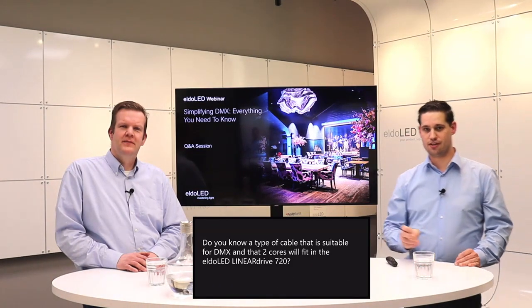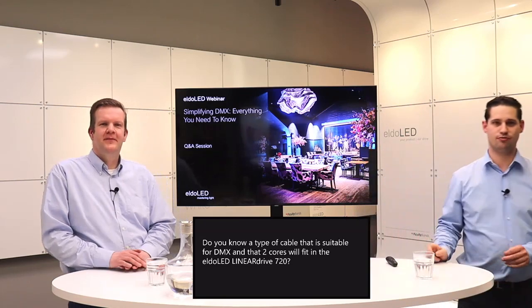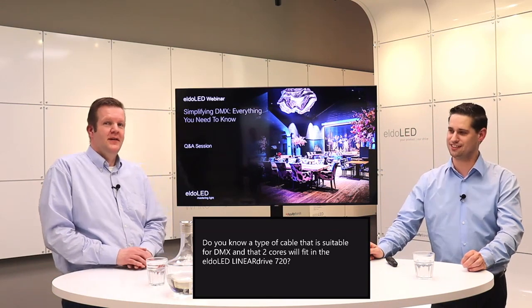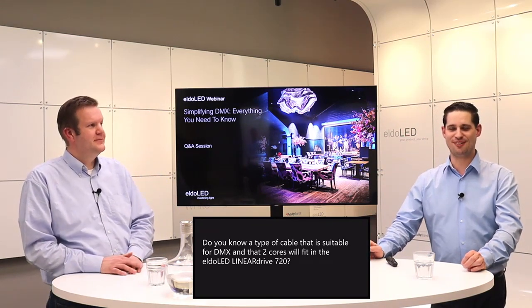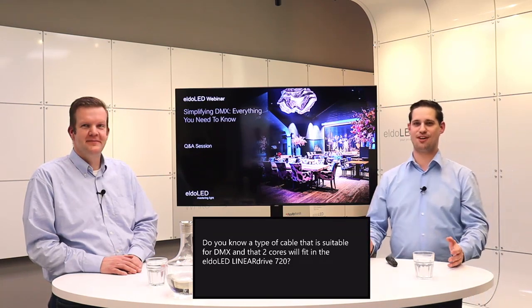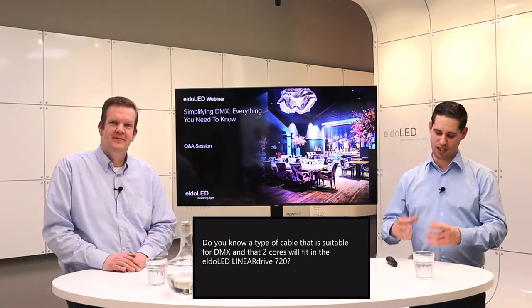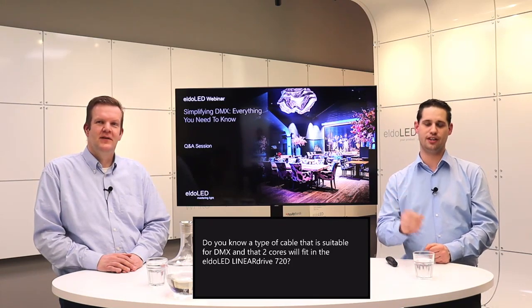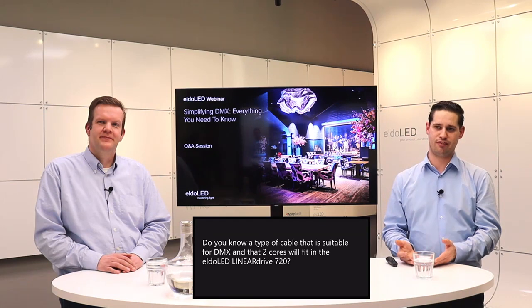Do you know a type of cable that is suitable for DMX and that 2 cores that will fit in the eldoLED linear drive 720? You're touching the right point. I don't know who asked the question, but that's something I ask myself every week when I'm looking into a linear drive 720. Those terminals are really small. But that was because we needed to add DALI and DMX and an external input on exactly that same product, so there was no size for a bigger terminal.